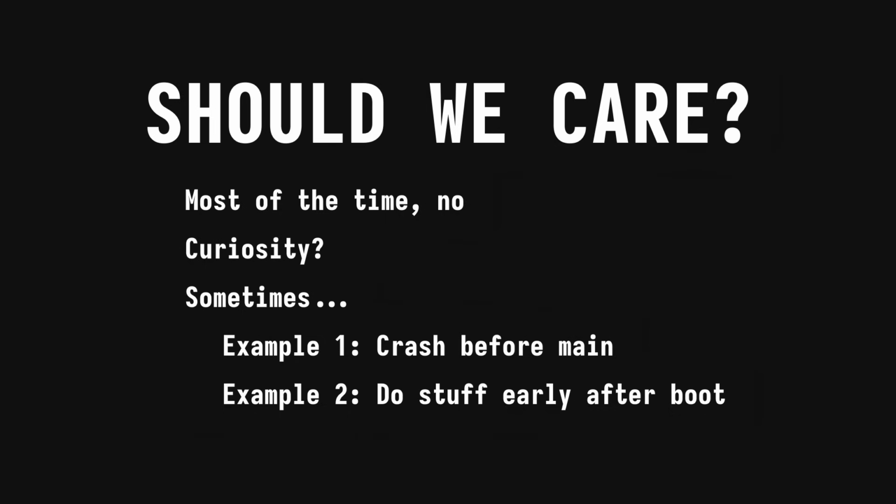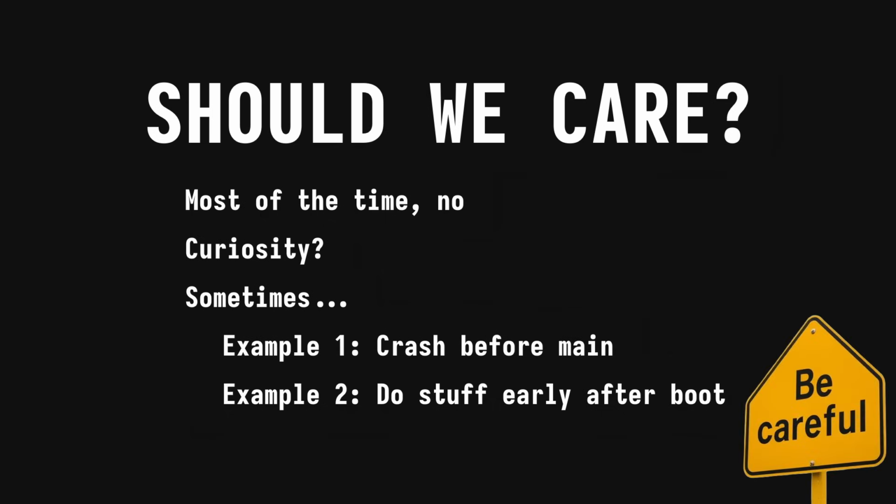Finally, a question that still might linger is if we should care about this at all. The truth is, in everyday development, we typically don't need to bother with what happens when a microcontroller starts, because someone else handles it for us. But if curiosity isn't reason enough, there are actually times when it's helpful to be familiar with it. Like when a crash occurs before main, or when you have to perform tasks early in the boot process. However, if you do need to modify the startup code, be careful, as it's easy to introduce subtle bugs. So understand how it works, but maybe avoid changing it unless you really need to.